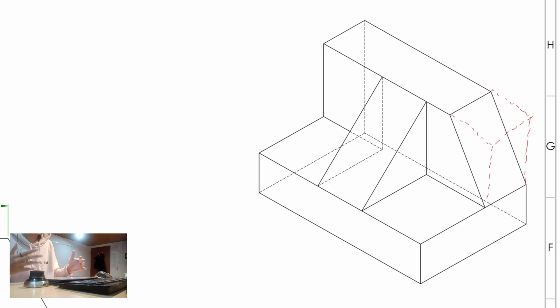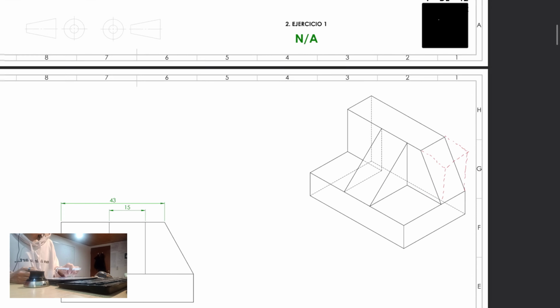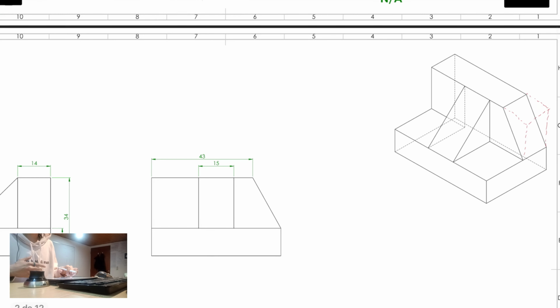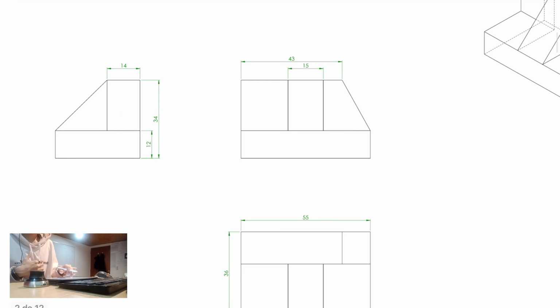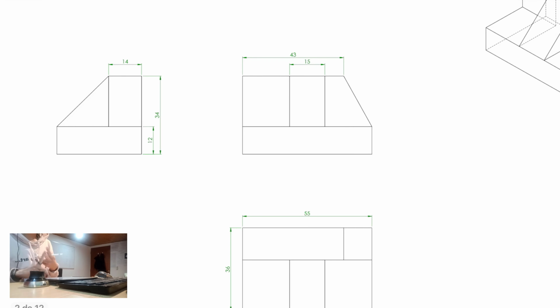We're going to start creating the sketch of the lateral view, and extrude. After that, we will create this pyramid or triangle, and later we will do the pocket. All right. As always, we're going to take into consideration the information within the engineering draw. First, we need the unit system. Second, we need the dimensions.